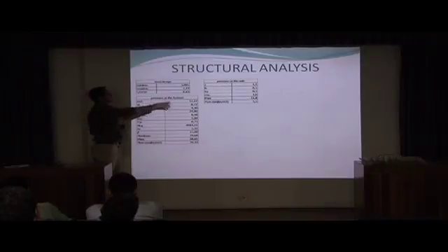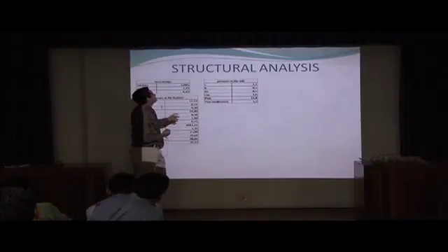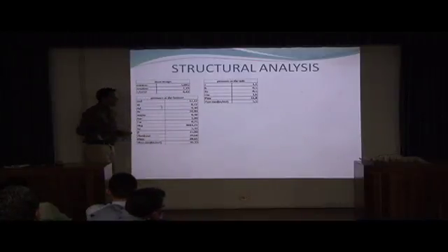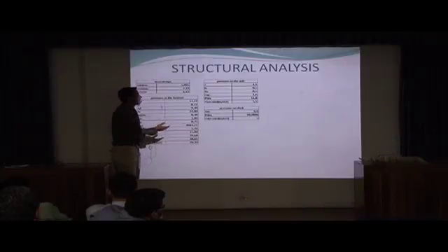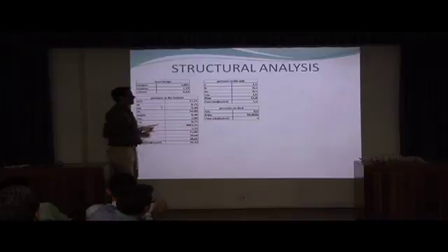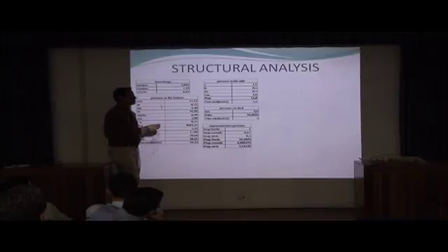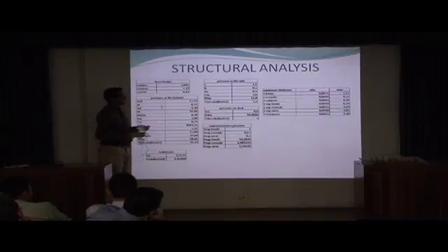For example, the pressure at the bottom is 26 kilonewtons per square meter. The pressure of the side, the pressure of the deck, and I have all of the pressures around the ship. Why do I calculate the pressures? Because it is so important for the article to get the thickness of the plates. Here are all the pressures, that is so important, and then